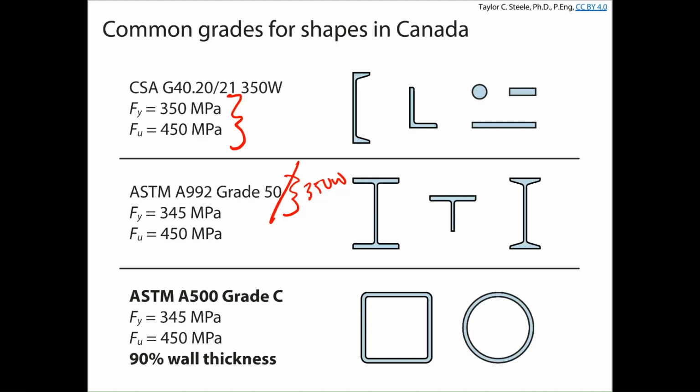That's right. So the hot plate will cool quickly. They'll roll it, they'll weld it, they'll heat it back up, and then cool it very slowly. When you hot work and weld the seam, you introduce a different kind of residual stress in the cross section. The welding heats up the seam, that pulls things together. And so if you want to get rid of that, you can anneal it and get rid of that initial stress state and also make it a bit more ductile.